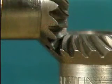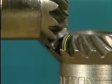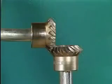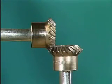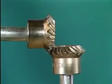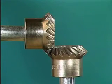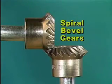This design increases the surface area of the teeth and allows the teeth to engage more gradually. Since the teeth engage gradually, the noise produced by the gear set is reduced. And since the gear teeth are twisted, more gear teeth can be meshed at the same time. This increases the load that the gear set can transmit. Bevel gears made this way are called spiral bevel gears.